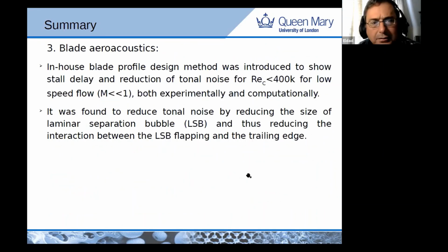For the blade acoustics, we looked at the method that we designed. The idea of the method is that you have to have smoothness in the curvature. We claim that you can relate it to the second order of the potential flow theory. What we found is that it delays stall, but in terms of acoustics, we found that it can reduce the tonal noise, and that was by reducing the size of the laminar separation bubble. And that reduced the laminar separation flapping, the interaction between the laminar separation bubble and the trailing edge.